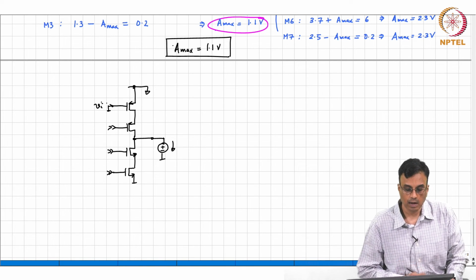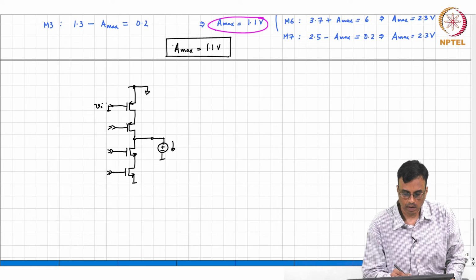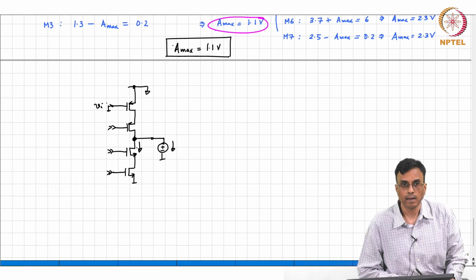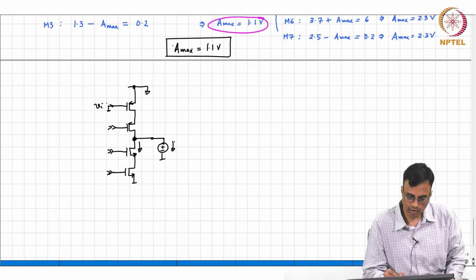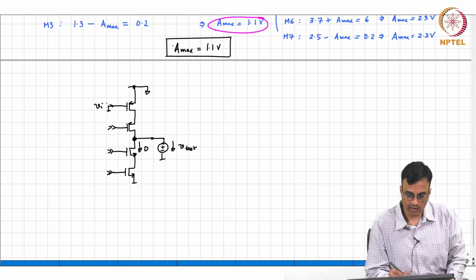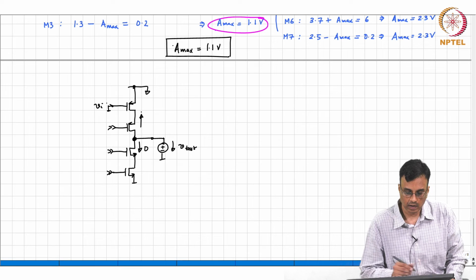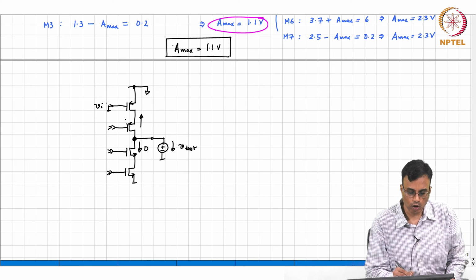This is Vi. What is the incremental current flowing there? Yes, the VGS of all these transistors is 0. So basically, this incremental current is 0. When we put Vtest here, the incremental current here is 0. What comment can you make about the incremental current there? This is basically nothing but a common source amplifier feeding into a common gate. We discussed this in the context of a cascode before.